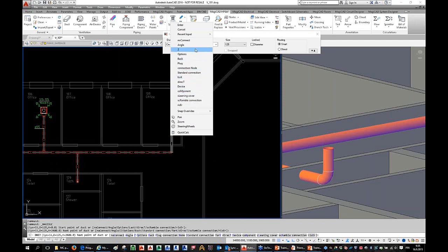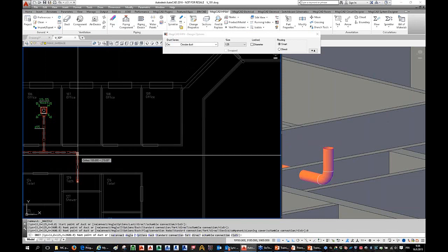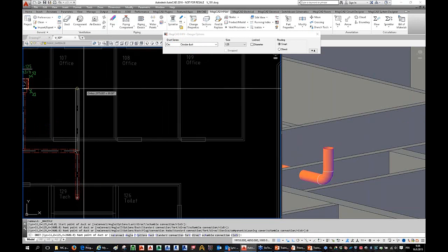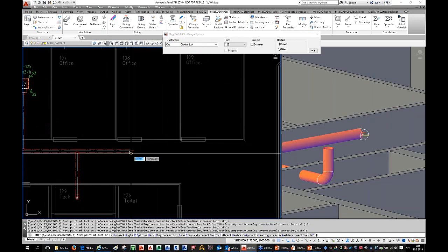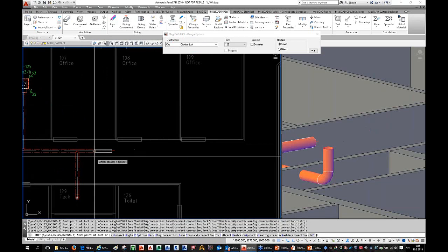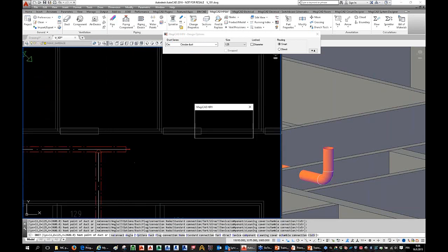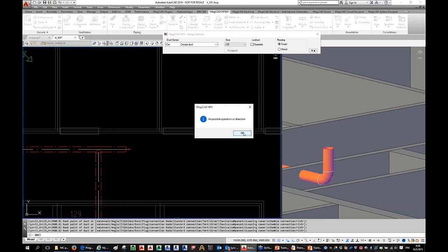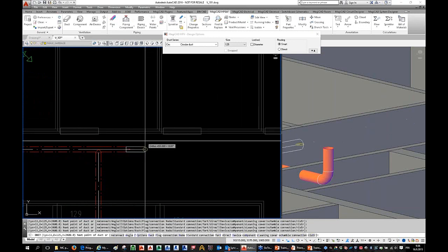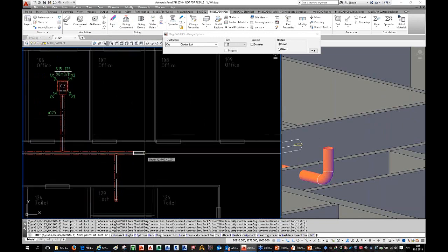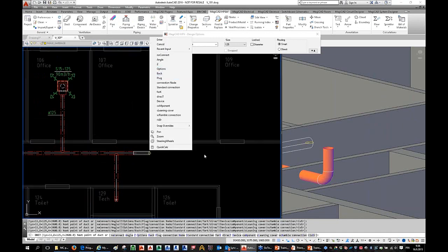And here you can see, for example, our back function, which basically reverts to the previous situation. And I can change the direction if I want, for example. Of course, you can draw backward also, but you can't draw over the branch or bend. You get an impossible operation or direction. So if you want to reverse like the bend or outlet, then right click and back.